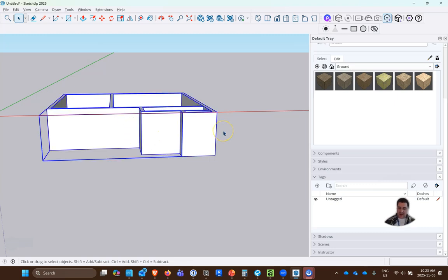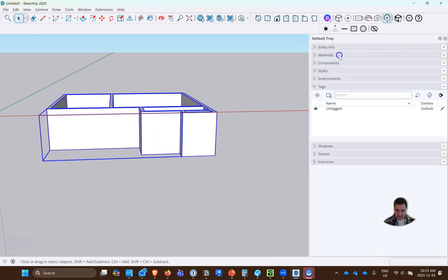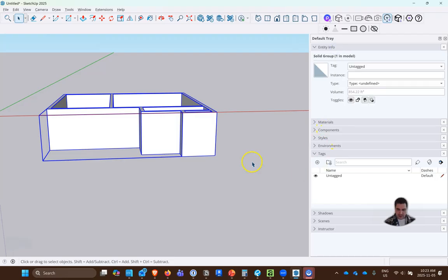But we will be doing tags with this. So let me just hide my material panel here. And so we have our walls here. And I think tags are a great way to stay organized. Groups, I'm not really that concerned with groups. Groups are just a way of keeping things together. But tags will be ultimately a little more useful. And so what I'm going to do here is I'm going to create a new tag. I'm going to call this walls-foundation.